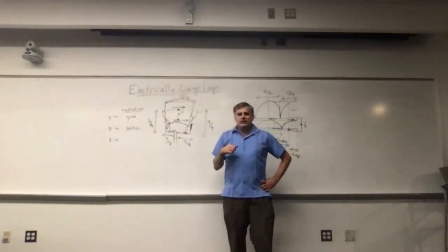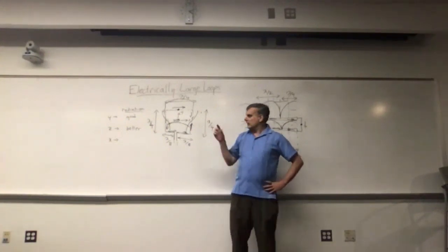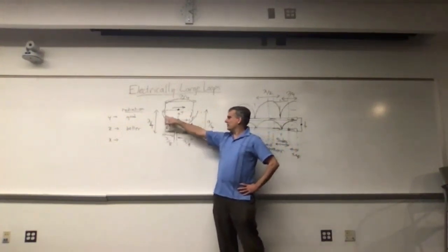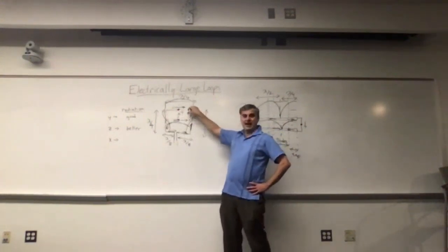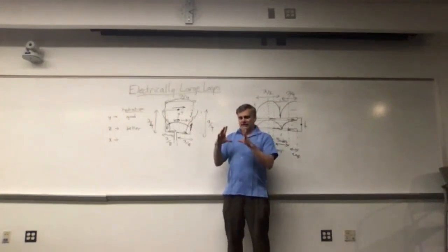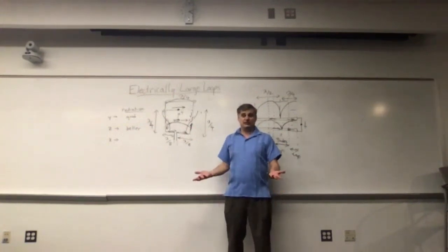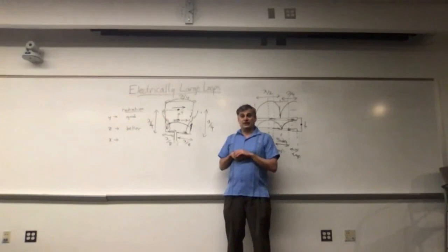And you get very similar behavior if you try a lambda circular antenna. I think for show and tell last class period, I brought in a little loop antenna that was electrically large, that had 360 around here, but then had capacitive breaks, bring it down a little bit more, confine the current a little bit more. There's a lot of really interesting games you can play with loop antennas, even though they're fundamentally very simple. Do a lot of interesting things with them.